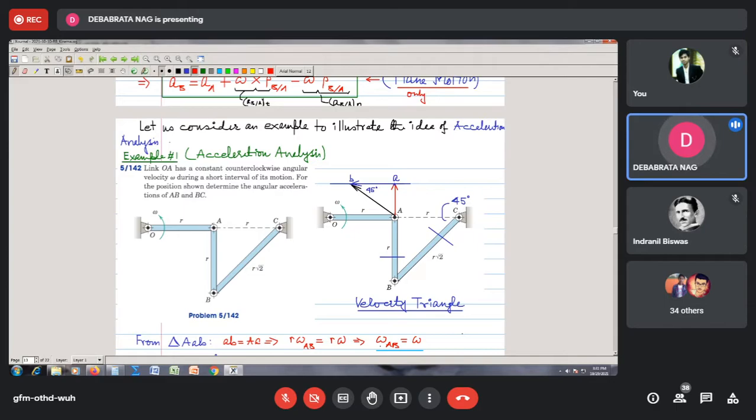These are all building blocks of robots. So all the robotics that you people do nowadays, there is a trend. Young people are very much interested in doing some robotics or robo hackathon, something like that. So you see, all the building blocks to that kind of thing are these four-bar linkage mechanisms. So by some external source, through the electric motor, I am giving the input motion to this crank, and I am trying to get the output motion here. So this is what is called the driving crank. This is called the driven crank, and this one is now termed as the connecting rod. So the connecting rod is connecting the driving crank and the driven crank.